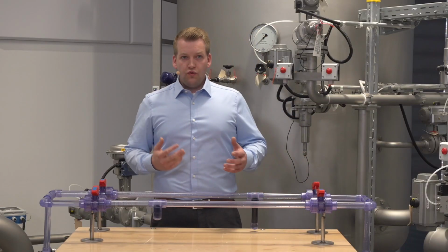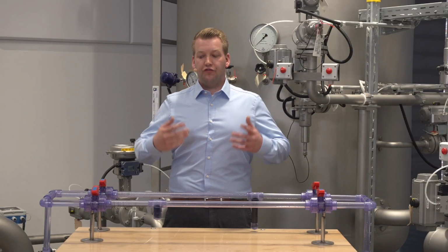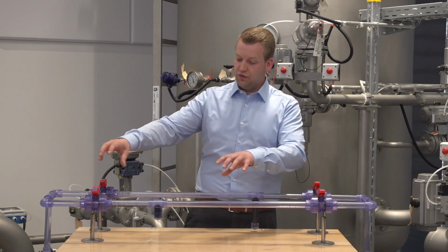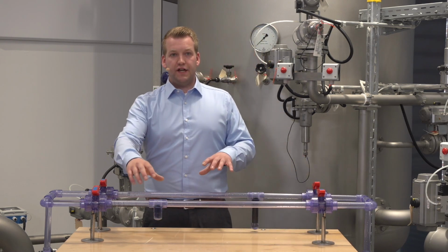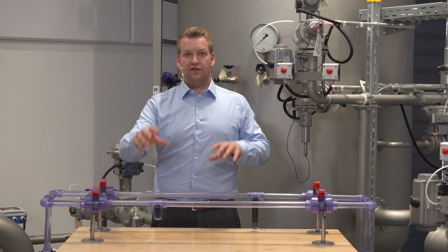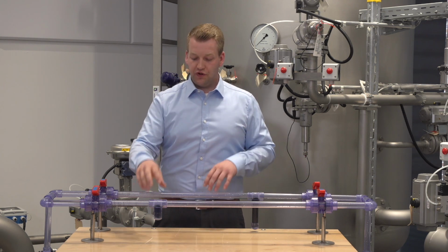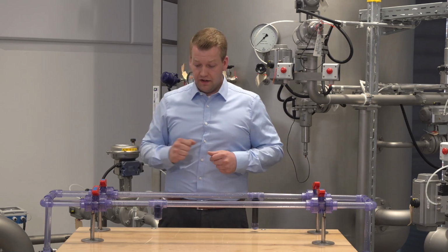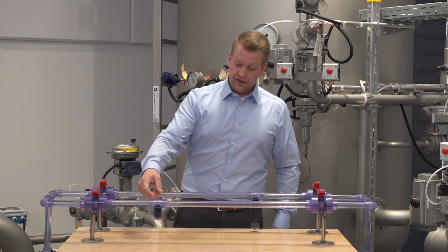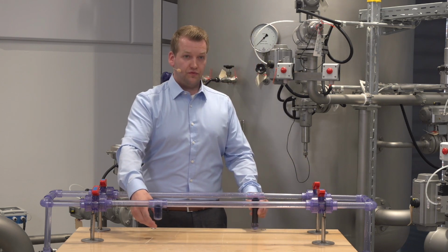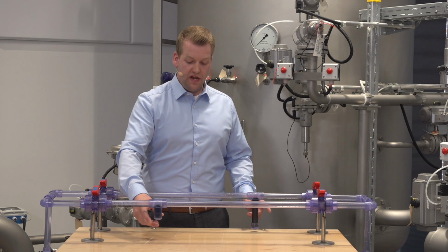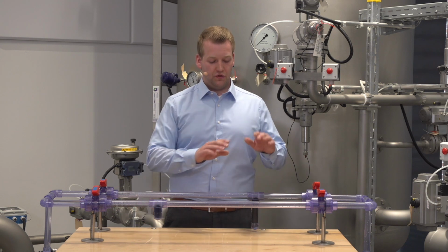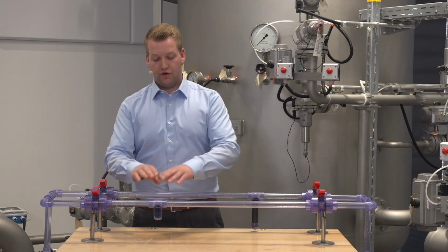What I will do now is flush some water and cleaning product through the pipeline of your plant. Every flushing and cleaning process here runs for 30 seconds, and then we can compare. One sentence again: we have 1.5 and 6 as dead space ratios. We have the same inlet diameters here, but different lengths, so it is 6 here and 1.5 here.